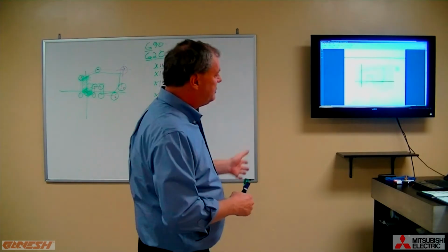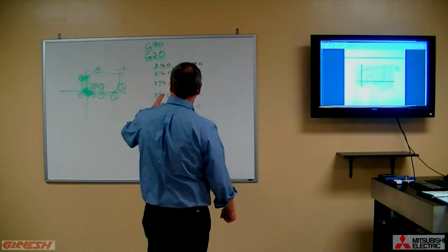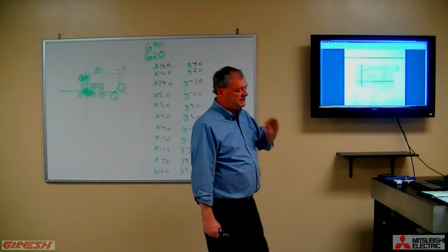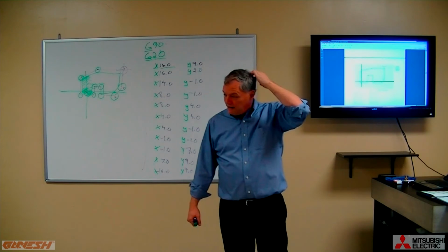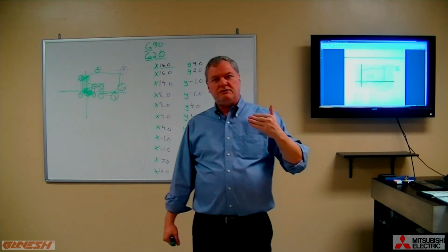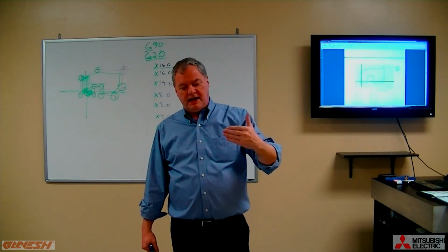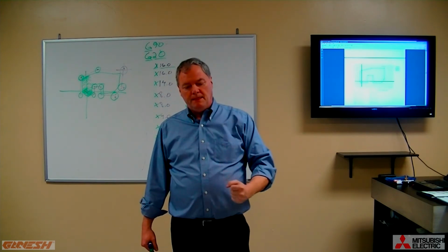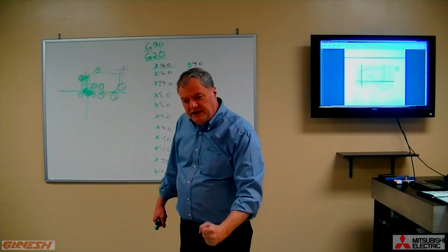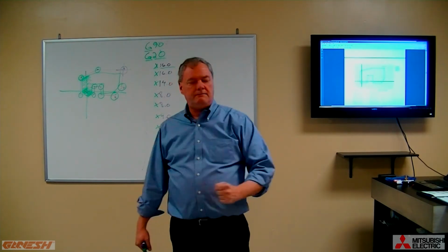So on the NC machine, there are two kinds of motion that you can consider. Rapid travel motion, which you can think of as traveling on the axes where the tool is not in material, and then traveling with the tool in the material at a feed rate.